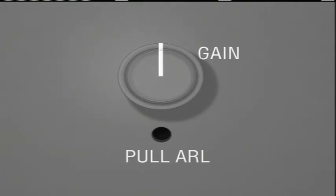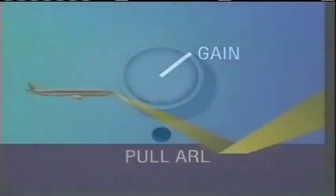The RDR 2100 is configured at installation time to be enabled or disabled in the weather mode. Warning: pilots need to be aware of their aircraft's system configuration, because the gain control reduces the sensitivity of the radar unless it is turned fully clockwise. Whenever possible, it's good practice to sharpen your mapping skills on known ground targets in good visibility.